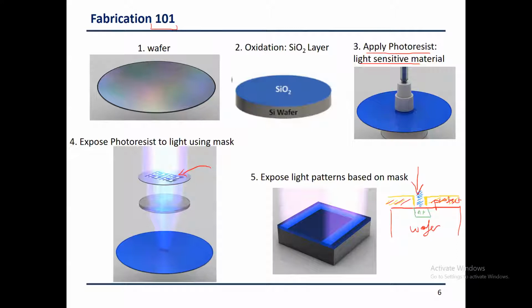Okay, and then I level the surface. So when I level the surface, I can then make sure that I have already my connections or my pins here, ready to connect this to any metal wire that will be drawn in the second layer. So any metal wire that will go to another node now really has a pin here which will short it too. Okay, so things happen in layers, things happen in steps.